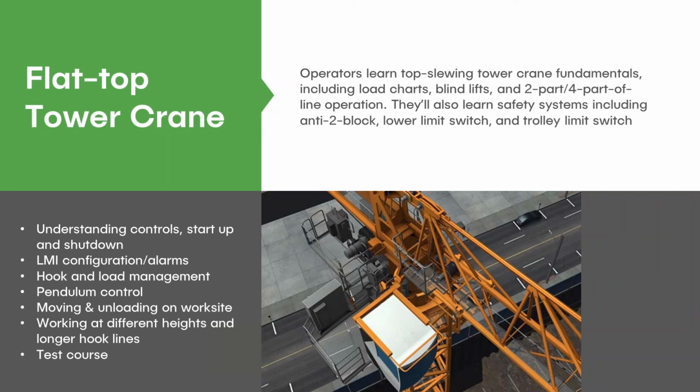The things that are really neat inside here, you get rope slack that is calculated depending on the load. If you jerk your load up too much, the rope will slap the boom. Any tower crane operators will know that one. The mast will kind of corkscrew when you have a heavy load and you're starting to slew. So all that's inside there.